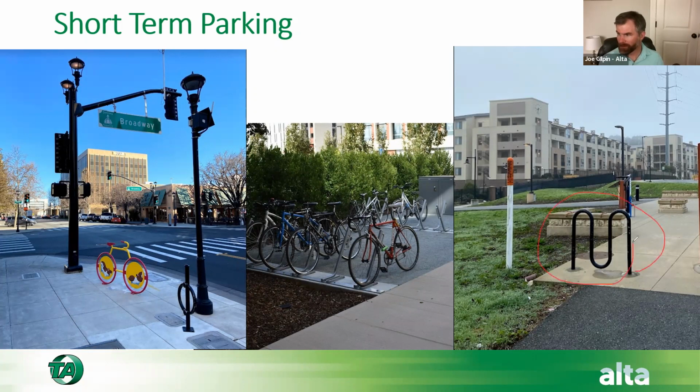The example over here, this wave rack, is not really considered best practice. Basically, you want 2 points of contact between the bicycle and the rack, so that the bicycle doesn't rotate and fall over due to the lack of support.